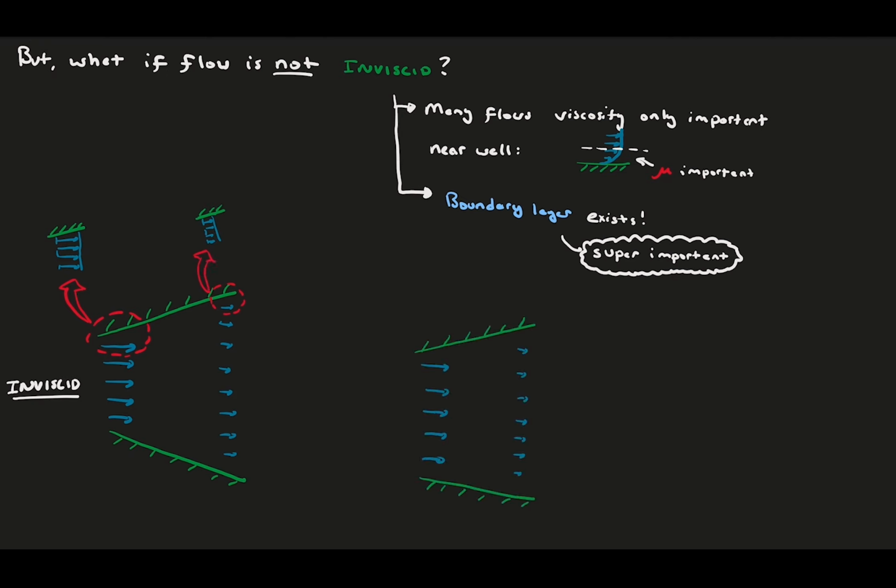That means, in the region near the wall, the velocity is in a deficit, meaning it is lower than the free stream velocity. As the adverse pressure gradient pushes back on the entire velocity field, the region in this boundary layer can't fight back as much because the velocity is lower near the wall. At some point, the velocity just above the wall reaches zero, and can even reverse direction. The more the flow slows down, the more of the boundary layer reverses direction, meaning flow backwards. The point where flow stagnates and starts to reverse is called separation.